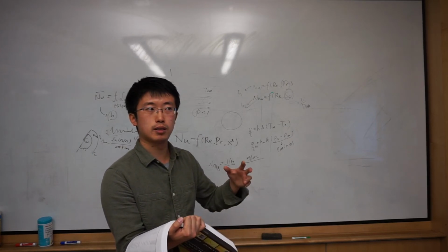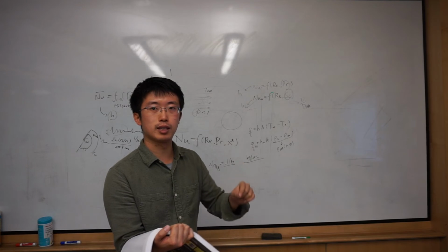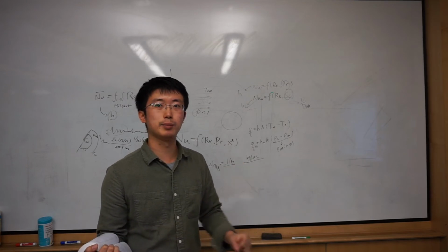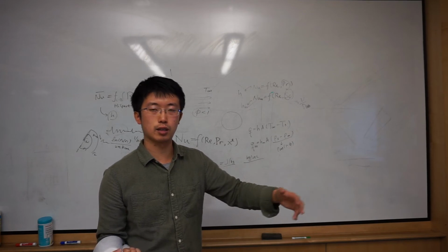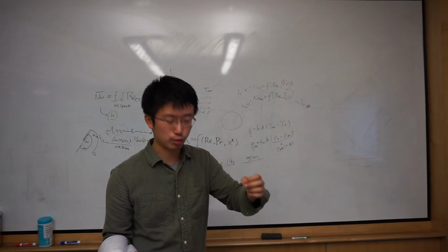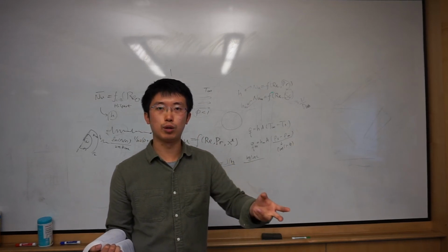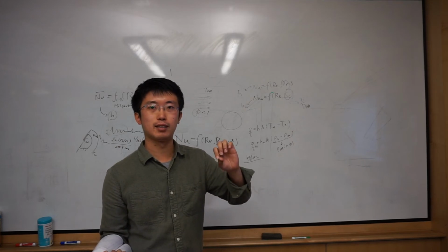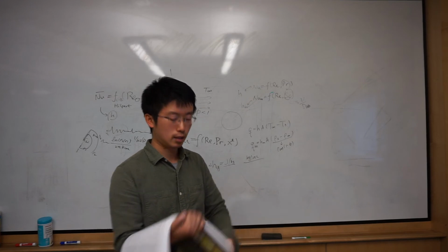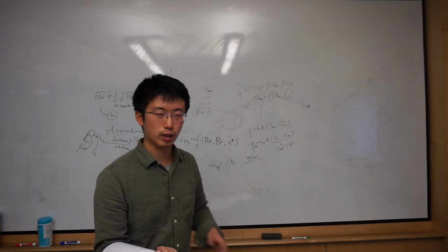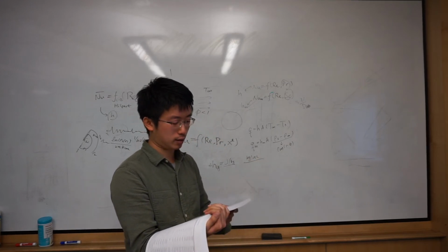The main difference is the boundary layer development is not limited by the surface on the other side, right? In contrast to the internal flow, where we can define a fully developed flow. So for external flow, the boundary layer keeps developing, keeps getting thicker.